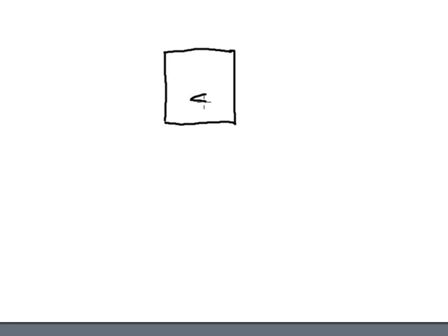I'm just going to write this with the Greek letter sigma for the sum operation, and it's got 3 inputs, A, B, and C in, and then it's got 2 outputs, the sum and the carry out. And inside this box is the circuit that we came up with that I just showed you in Quartus. You might see it in this orientation, you might see it flipped or rotated about 90 degrees, but this is the general idea. 3 inputs, A, B, and C in, 2 outputs, sum and carry out.